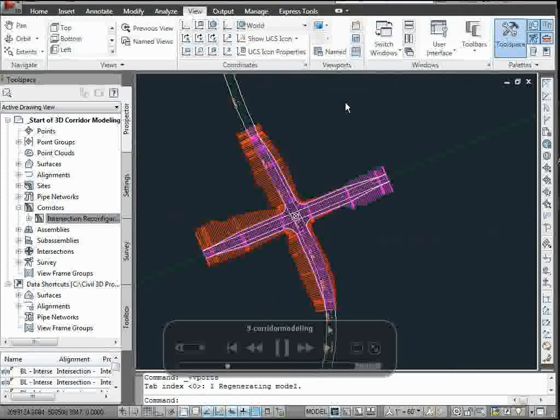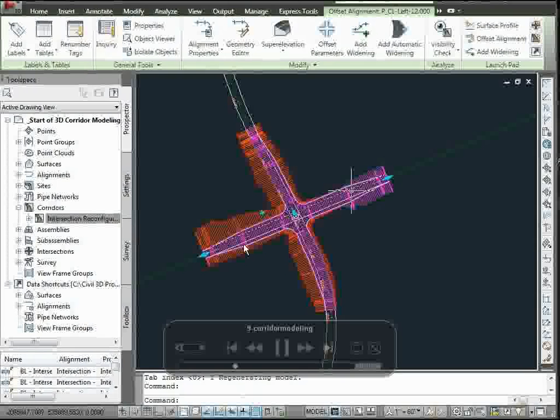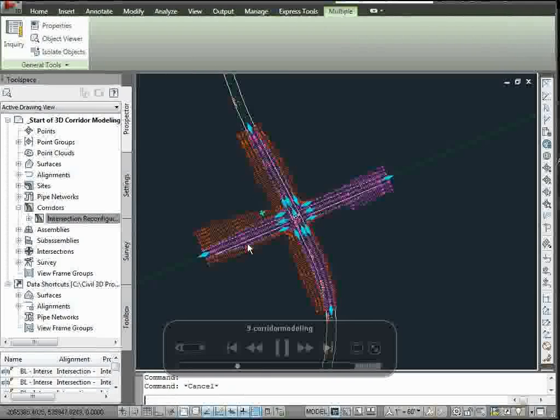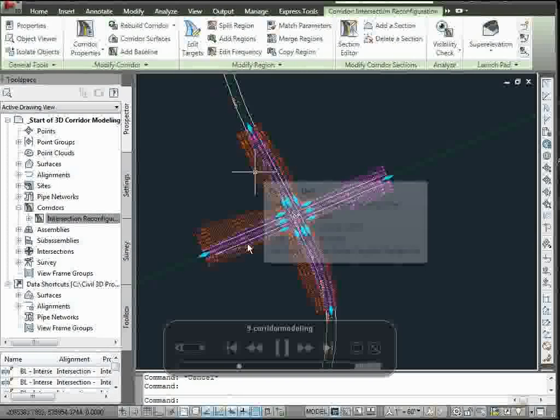So you can take these typical sections in, and what you do is you can combine them with our corridor process. So we take the typical, we put the horizontal with it, the vertical with it. We have it target a surface, which would be from that GOI and I-cubed, and that's what we're using to target right here. And then when we come in here, we can grab this, and almost everything in Civil 3D is where you can touch it.